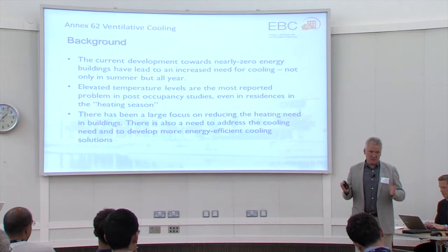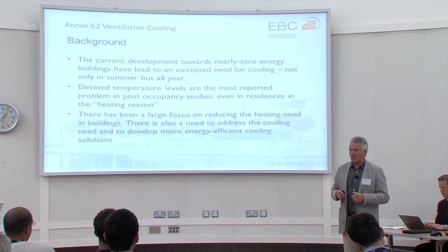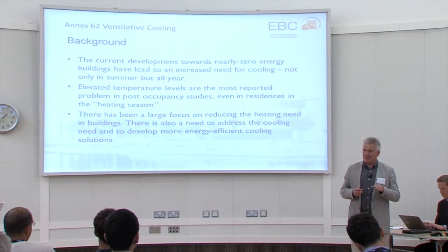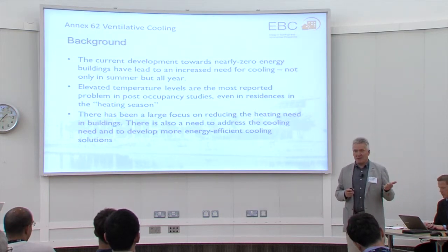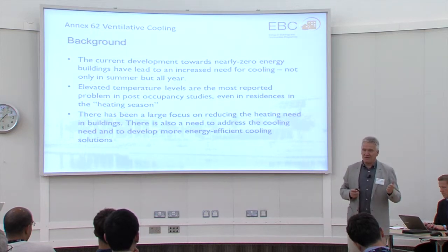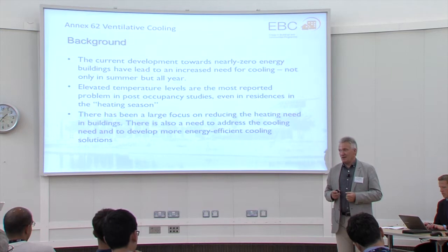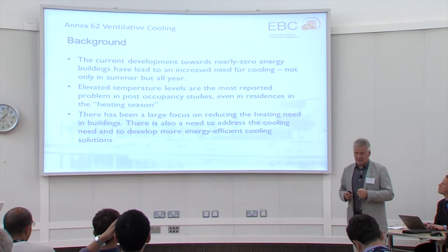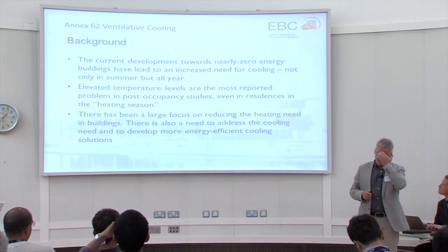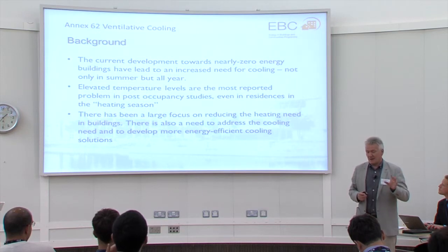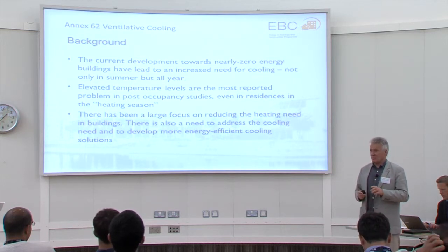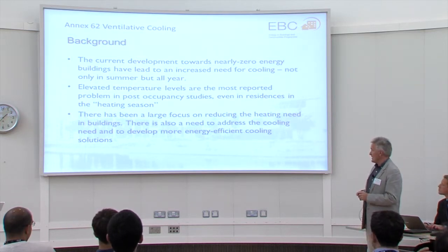We focus a lot on decreasing the heating need in our buildings, because this is the dominating energy use in our buildings. And what happens when we optimize the heating need is that there is a side effect that we sometimes increase the cooling demand, or if we don't have any cooling, then we might increase the temperature levels in these buildings. And if we look at some of the recent demonstration buildings which are fulfilling our future goals for energy efficiency in buildings, we can see that elevated temperature levels is one of the bigger problems in these buildings.